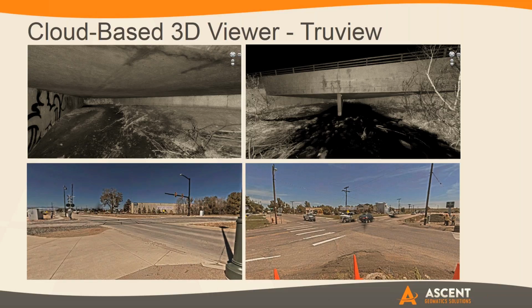within those, so you can get design level detail out of it. A lot of people are trying to use LiDAR within UAVs as well. It's generally not going to be quite as accurate, so if you're looking at a large scale area, more of a generalized surface model, it's great for that, but when it comes to getting that kind of curb and gutter detail, the systems aren't quite there yet, so that's something a lot of people ask for whenever we're talking to them about this.